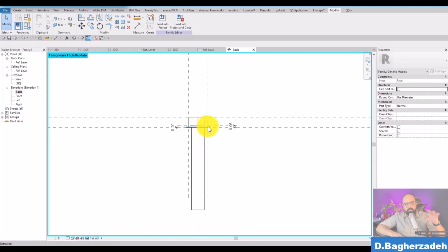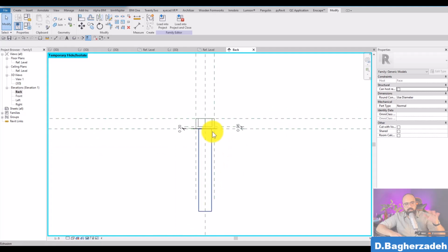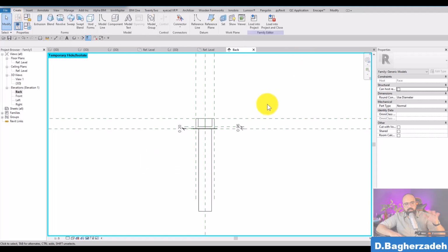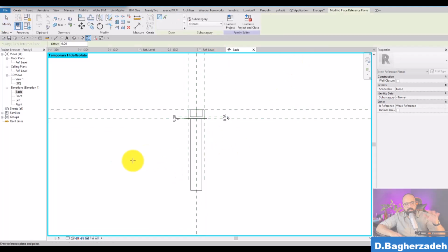There is a height for the screw, which we need to have the nut in the end. When we have 2 or 3 glasses, each one is 6 millimeter. For example, when we have 2 of them, 12 millimeter, and we have 2 sheets, we need to have the screw through all of them, and after them, the nut.